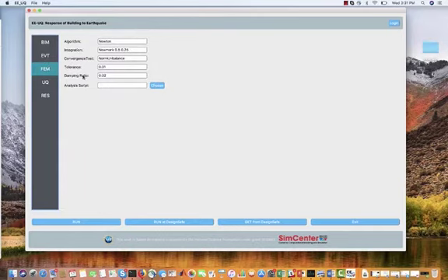After the event, you have to go through the analysis options. Basically, what is your solution algorithm, your integration scheme, what is your convergence test, your tolerance in the convergence test, and of course the damping ratio. So let me change this to 4% damping. You also have the option to specify an analysis script. If you don't like the analysis script that's set by default, you can come in here and change that analysis script. So if you have an analysis script which just does the analysis, you would select it here. Otherwise, leave it alone.